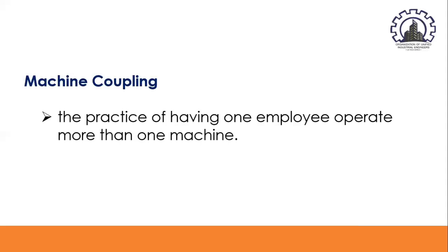Now, a break in the vertical work time line signifies idle time, and likewise, a solid vertical line under each machine heading indicates machine operating time, and a break in the vertical machine line designates idle machine time. A dotted line under the machine column indicates loading and unloading machine time, during which the machine is neither idle nor productive, as shown in figure 2.14.